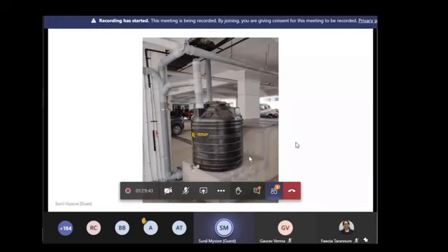This is again a settling tank. You can see there is a valve here, the first-time separator. Then there is this water. Essentially, the first minute of water is stored here. Then the water overflows into this settling tank, also called a rain barrel. And you can see a tap here. This water will be used for non-potable use. And you can see there is an air vent provided so that there is no airlock anywhere. And the overflow from this rain barrel will go into the filtration.